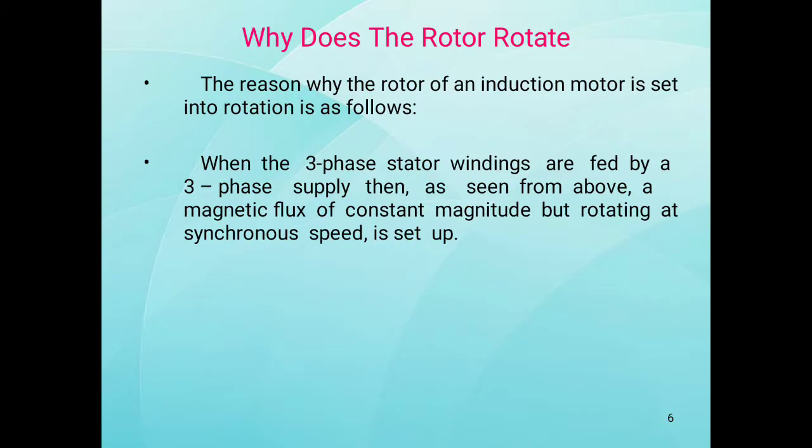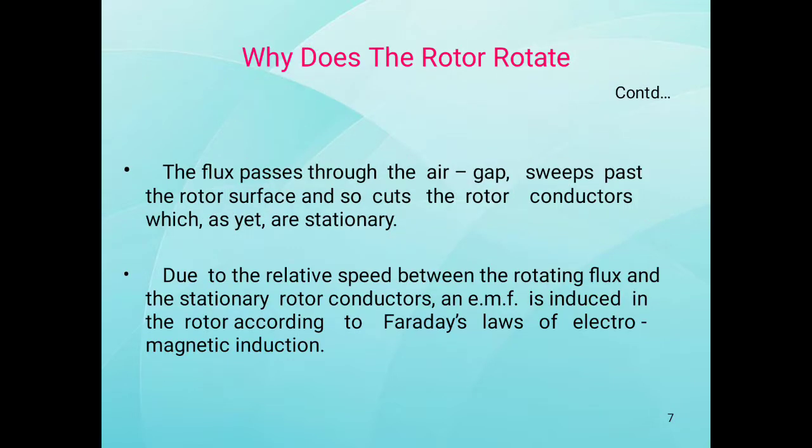So why does the rotor rotate? The reason why the rotor of an induction motor is set into rotation is as follows. When three-phase stator windings are fed by a three-phase supply, then as seen from the above, magnetic flux of constant magnitude but rotating at synchronous speed is set up. The flux passing through the air gap sweeps past the rotor surface and so cuts the rotor conductors, which as